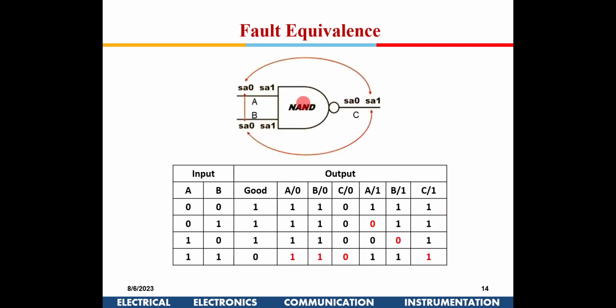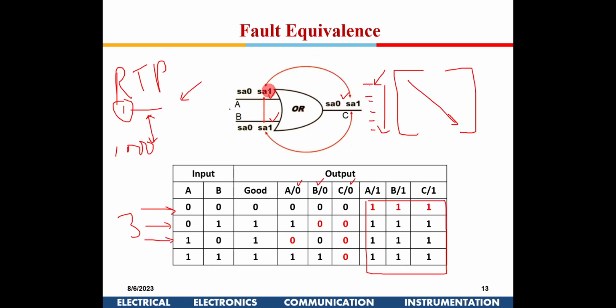Similarly, for now, if you see here, we know this theory. So wherever there is an OR gate, the tool will check for stuck at 0 and stuck at 1 here. So the tool will check for 4. It will generate 4 faults: 1, 2, 3, 4.